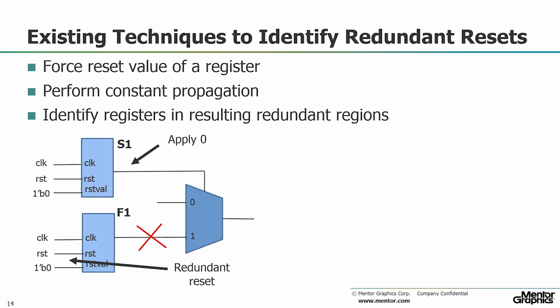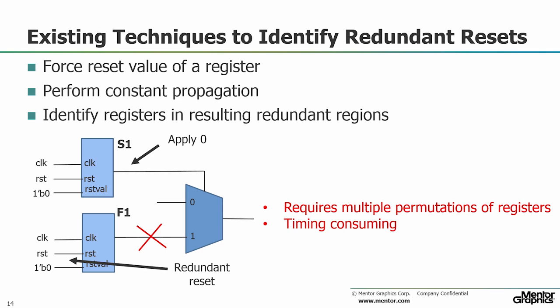But this method requires designers to try out a large number of permutations of registers on which the reset value is forced, and hence can take a lot of time in obtaining a meaningful set of registers from which resets can be safely removed.